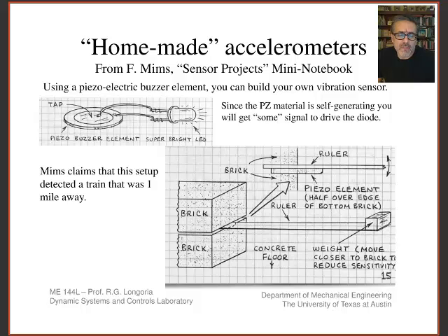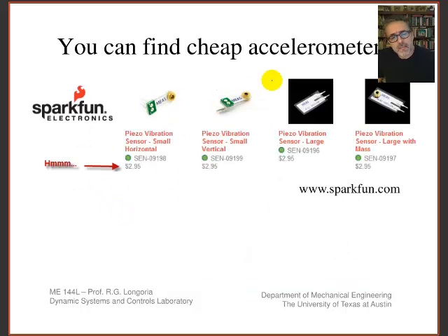And there are a lot of accelerometers nowadays that you can buy off many websites like SparkFun, and I'll show you some. Very cheap, and they're a little bit more difficult to use. You have to build some instrumentation around them, but it's worth it if you're building devices on your own. Oh, and here's an excerpt from the sparkfun.com site. There are these little piezo vibration sensors. Look at this, $3 for a very nice one. And what you have, this is a mass beam, and you have a little piezo film here. And these give really nice output.